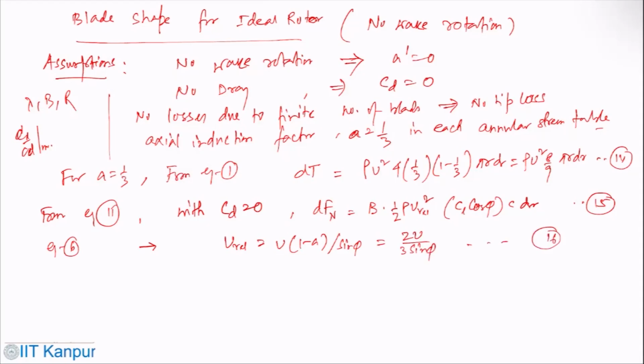That's now the blade element momentum theory, or strip theory, which refers to the determination of wind turbine blade performance by combining the equations from the momentum theory and blade element theory. Now, using equations 14, 15, and 16, we get C_L B c by 4 pi r equals tan phi sin phi.